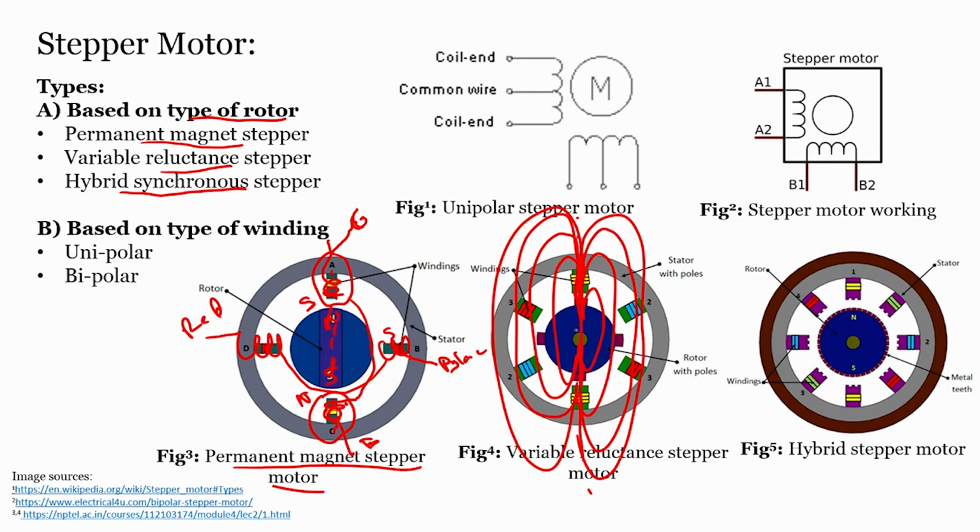this rotor shaft over here will always try to reduce the resistance or reluctance in the path. The magnetic field has to pass through this soft iron material, go through this coil and complete the loop, since magnetic fields are closed loops.